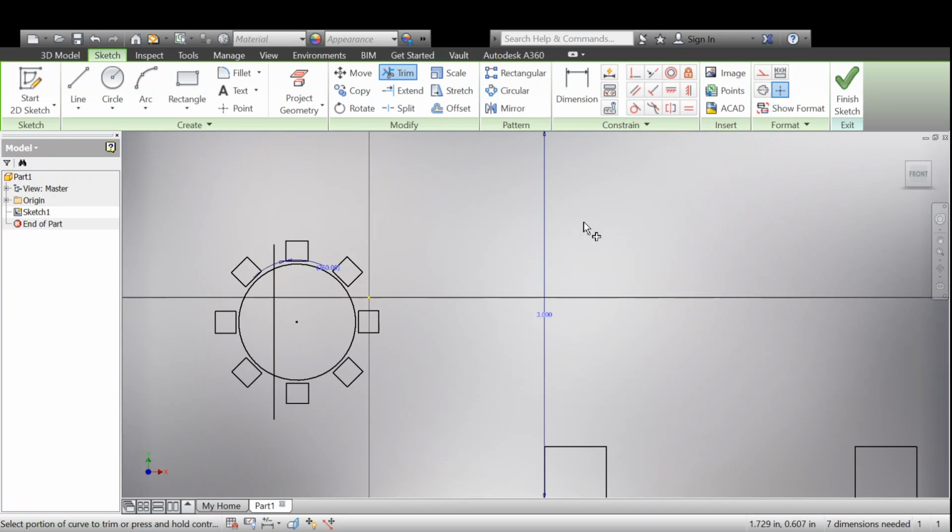Now I'm going to open your CAD file when you submit it, so I'm going to be able to look over here and see your features. If I see that you made 30 windows and didn't use the repeat feature, I'm probably going to say that's not the optimal way to do it. You follow what I'm saying? So do things in a way that looks good, but also try to use a lot of the features in the sketch palette that's up top. There's also one called points, where you can set points and use that to specify distances. Point is very useful as well.